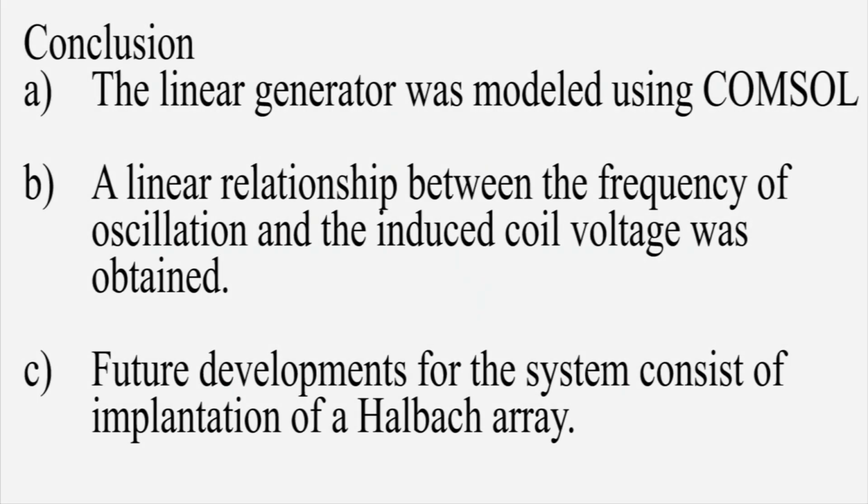In conclusion, in the linear generator model in COMSOL, a relationship was developed between the frequency and induced coil voltage, and for future developments, the implementation of a half-Halbach array can improve the system's operation.